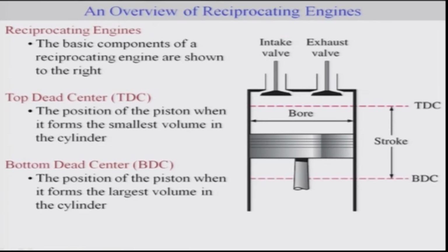Okay, so the inlet valve is this, where of course your fuel will be injected, and the exhaust valve would be where the combustion gas would be removed. This is your top dead center, the position where the piston forms the smallest volume in the cylinder, and the bottom dead center is the position of the piston where it forms the largest volume in the cylinder.